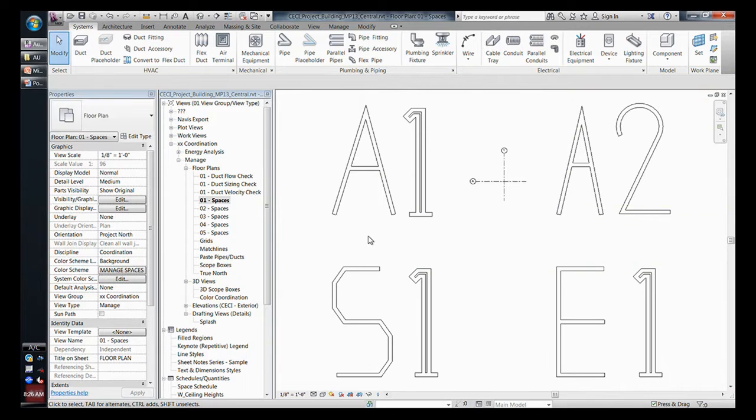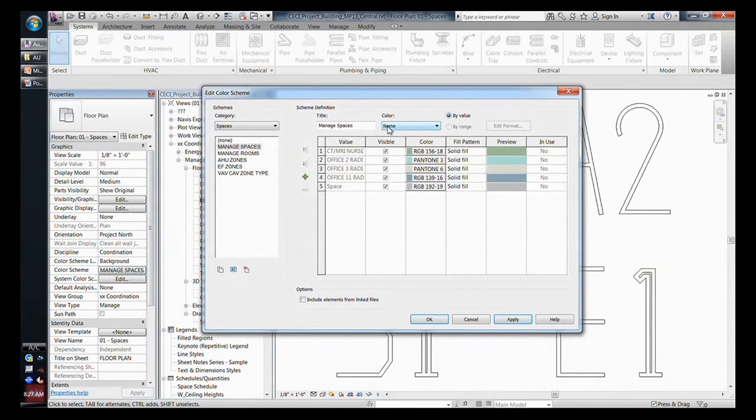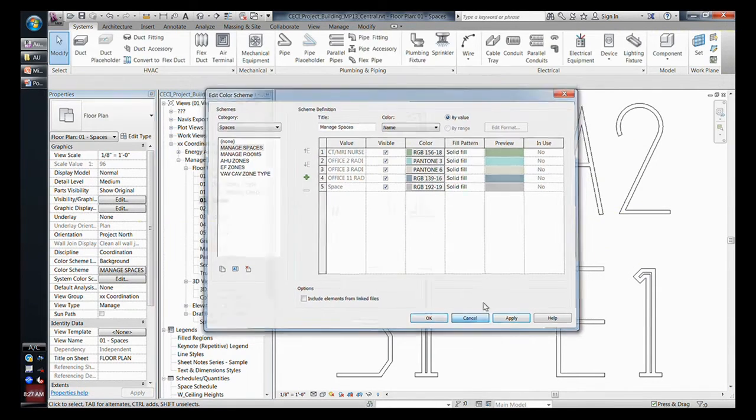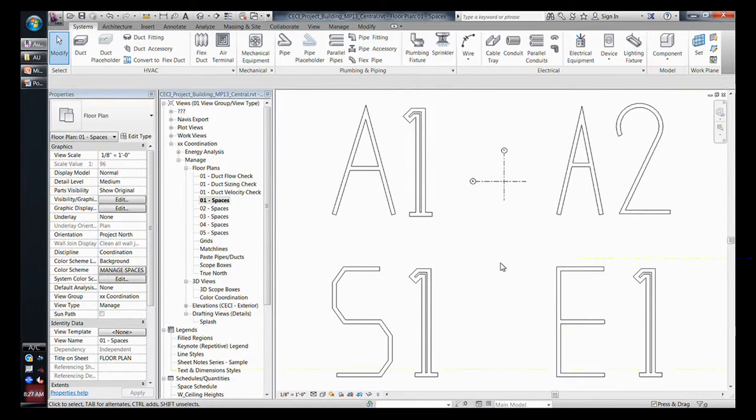Instead, what I'm doing is, for my space tags, I'm having them look at the room name and number. So the room name and number is always current. I don't need to do anything, and it's always being displayed. So having this color scheme look at your space name, which always remains space, that's the name of the space. All spaces will be called space by default. They all get one color. Therefore, you can see the entire architectural building in a single color. I really don't have great examples, but I'm hoping that you understand what I'm talking about.